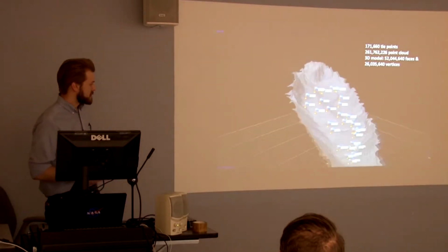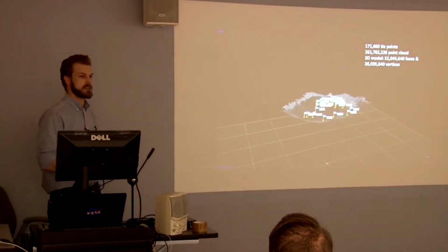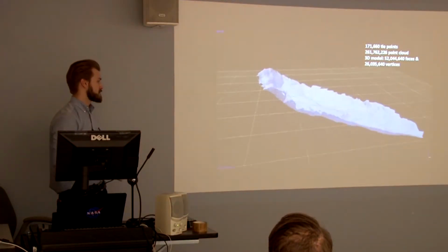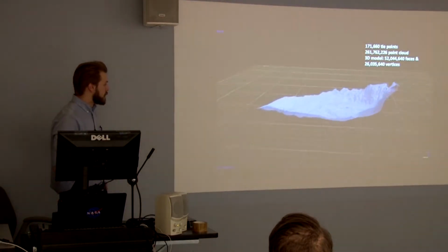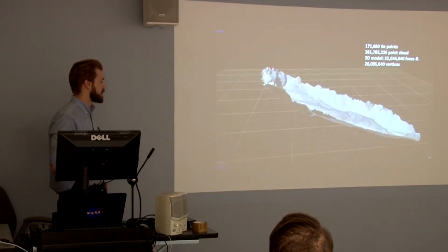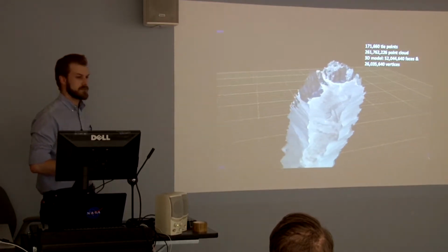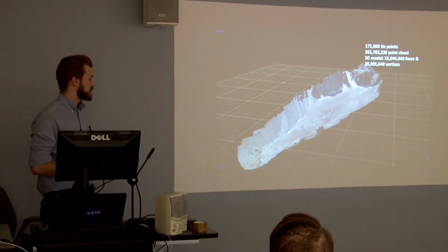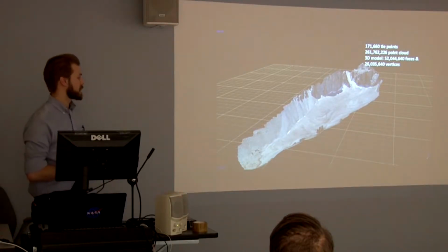So what this means is that we're able to use the structure from motion algorithms and the Ohio supercomputer's resources to stitch together these surfaces, form meshes, and eventually overlay the orthomosaic. We do that by tying it to those ground control points that we use, and evaluate the model using the accuracy points.